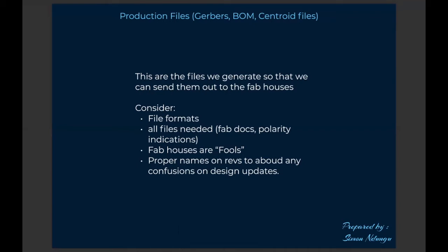Also, always know that the fab houses are like fools. I mean, those guys will only do what you tell them. They can't think beyond what you have given them. So even for some very simple logic, you will find them asking questions like, what do we place here? What do we put? I mean, it's a resistor, just put it there. So put proper names on the boards, just name your boards. Like if it's RF1, just name it so that you don't get confused when you're doing an update on the files.